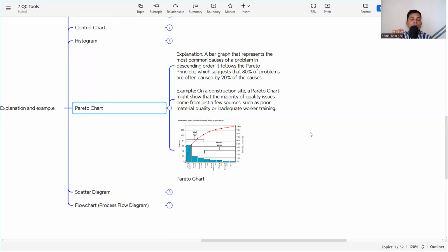Problem two, we need to know the competence of the worker, whether they are trained. Then we can find out the environmental data. Then we can find out the concrete temperature, the concrete curing time, and the deshuttering time. Now if we list it out one by one, we will see what the main reason for the cracks is.